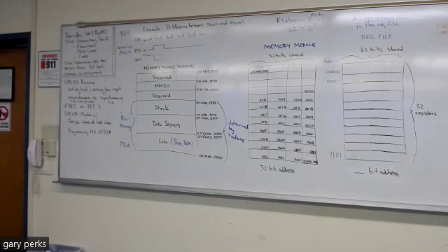Maybe this should be 3 bits instead of 2. Oh, no, the sign is bit 14. I see. So if you just look at 12 and 13 for byte, it's 0, 0, and for the other it's 0, 1. For LBU, unsigned, it's 0, 0 with a 1 for the sign, but when it's signed, it's all 0. So that's telling it whether it's unsigned or signed, and this is telling it whether it's a byte or a word. That's the other part of the memory module that's determined.